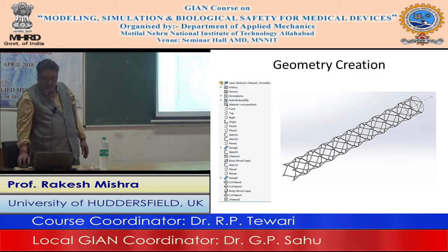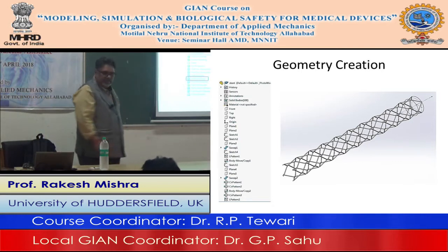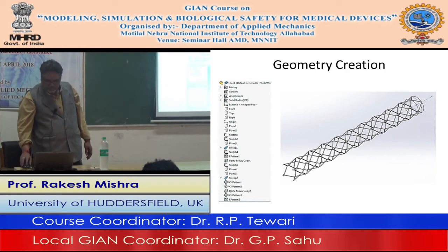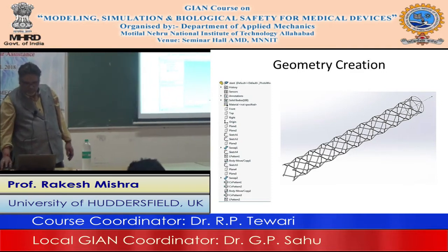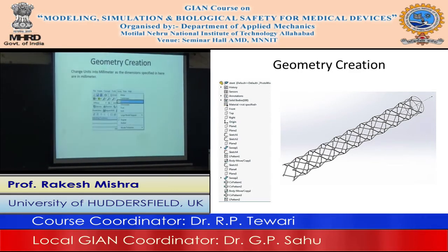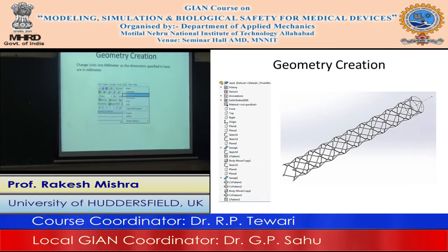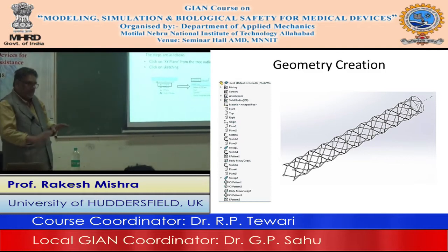Then we start the ANSYS like we did every day. Start the ANSYS, bring Fluent back here. So Fluent has come here, and then we double click on geometry, and if we double click on geometry, Design Modeler will open. A new window will open, and here first we create the display plane by clicking on the display plane icon, and once that is done, like we did every day, we change units to millimeters, and then we create the complex artery.